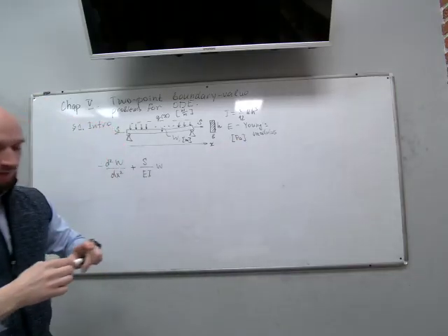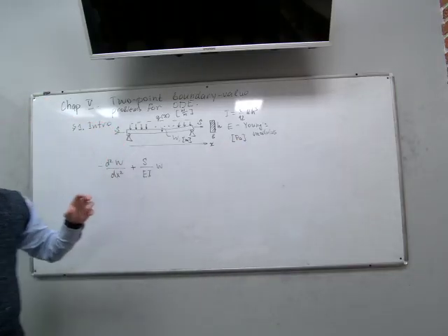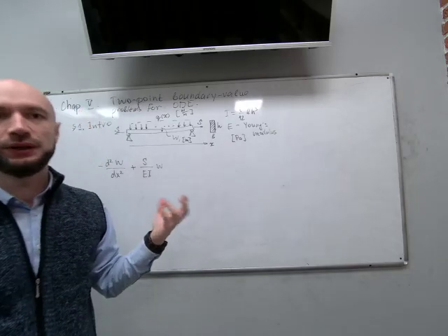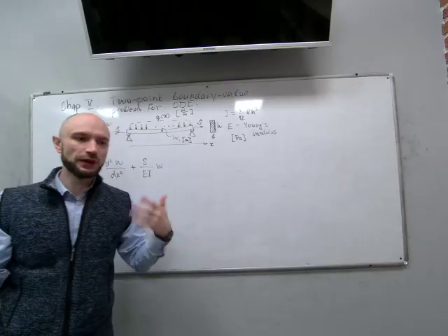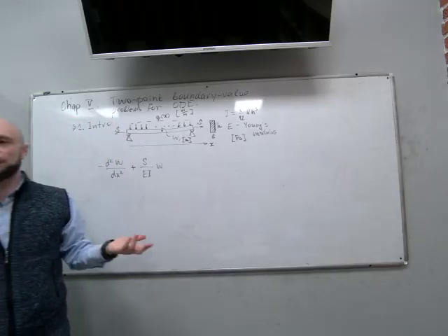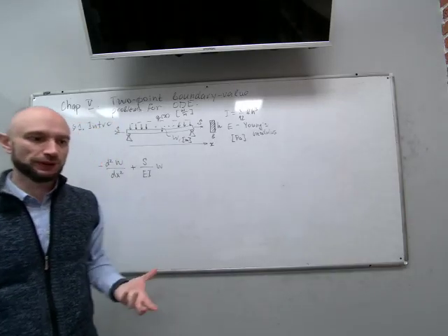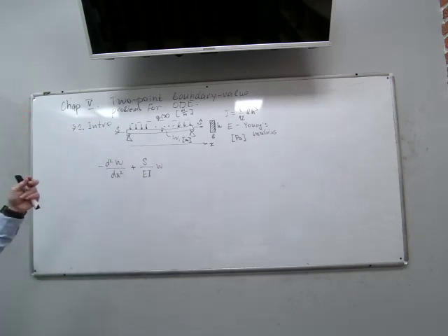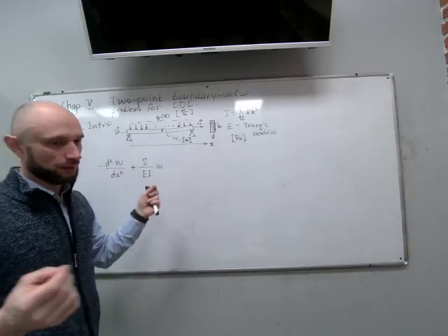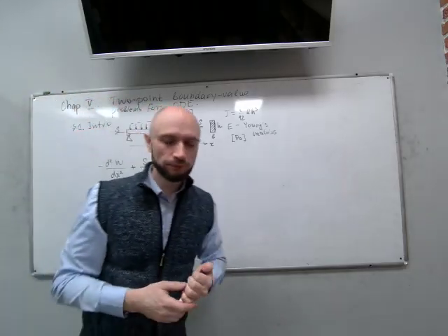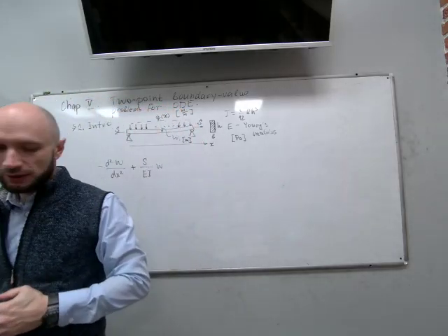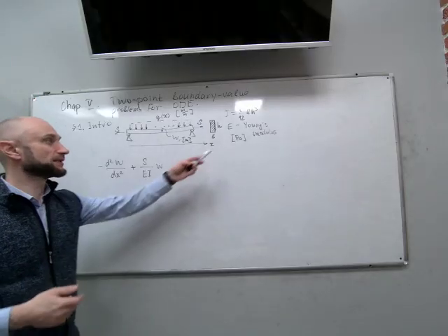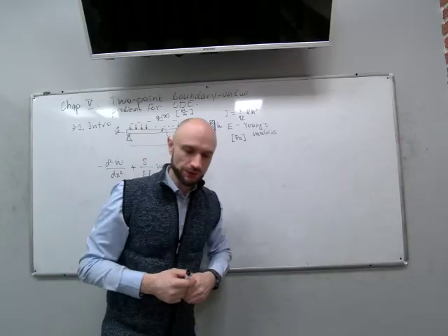So, what's Young's modulus? Young's modulus defines how large will be the deformation of an elastic object under a load of 1 Newton, for example. If we load an elastic object with some force, this elastic object will become longer in the direction of tension, and then how much longer it depends on the value of this elastic modulus.